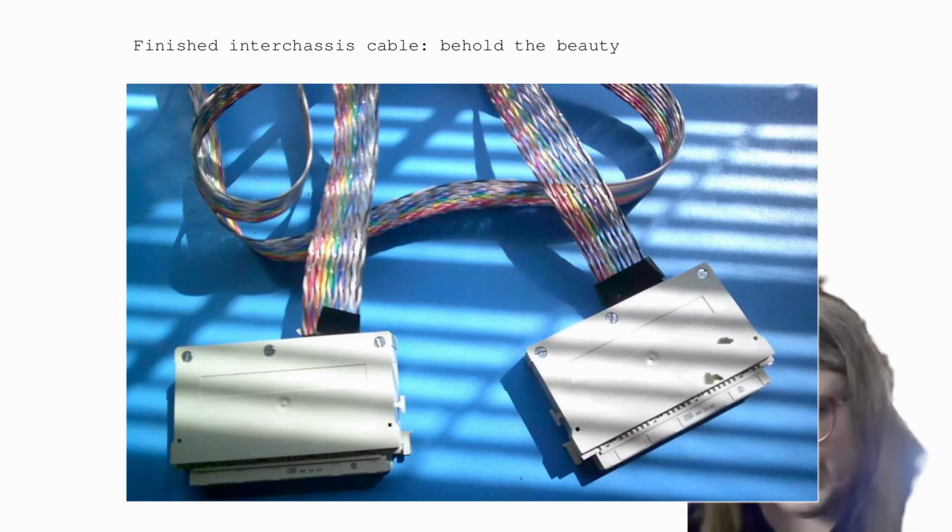And I don't connect all 96 signals here because it's a 96-pin connector. But I only connect, how many was it? 8 twisted pairs. So yeah, I had a cable with 10 twisted pairs. I ended up needing only 8. So 8 twisted pairs, 16 wires in total is what I have connected. And again, I used the documentation of the pin outs to figure out which pins I actually need and which ones I don't need in my minimal configuration.